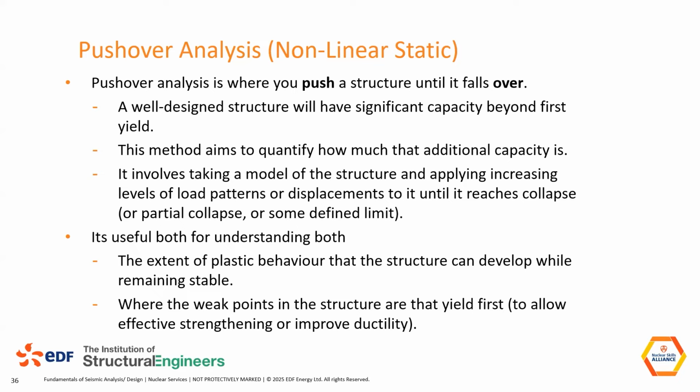You'll get plastic hinges forming. You'll get failure of elements. You'll get buckling. As long as the load can redistribute somewhere else, you can keep pushing, and you eventually keep going until you push it over. The advantage of pushover analysis is it tells you two things: how much capacity you have above the elastic limit.